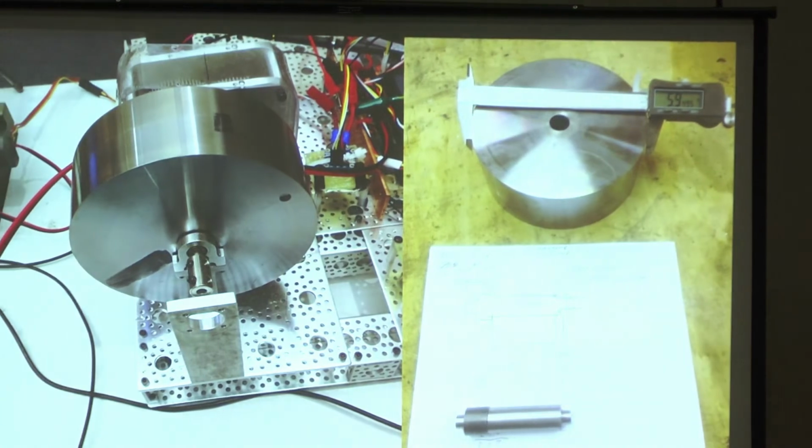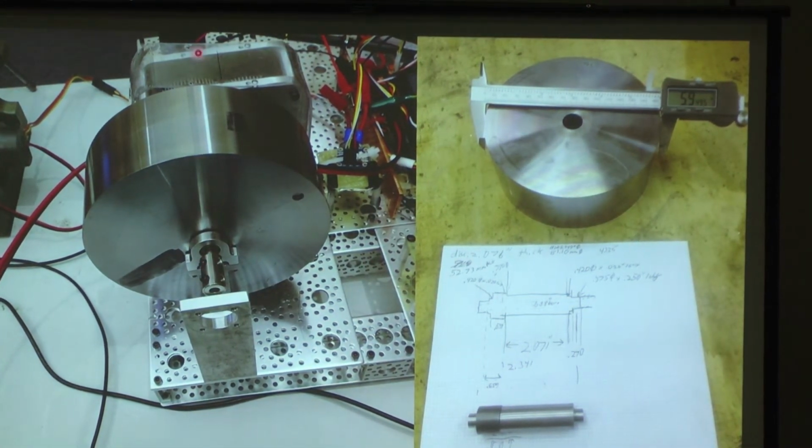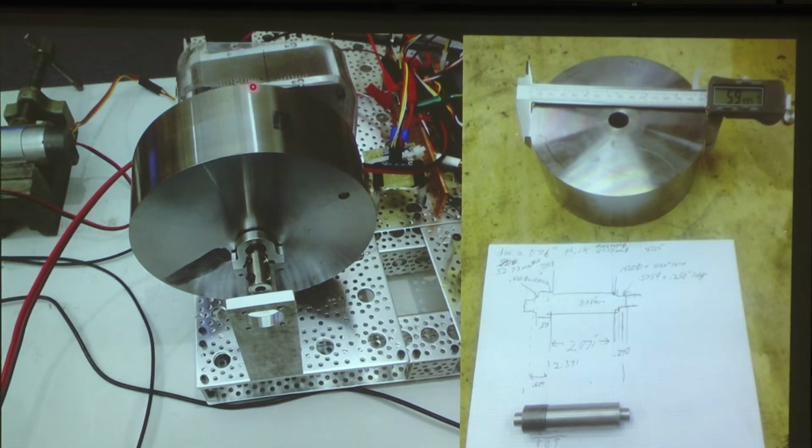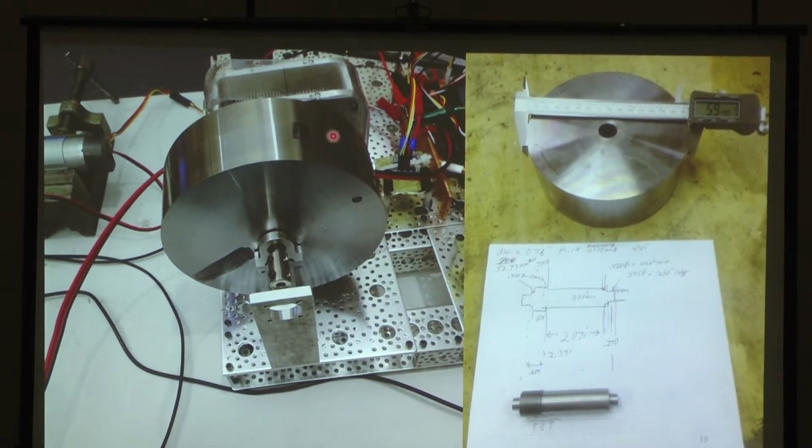So before we could collect any data, we had to manufacture many parts on our dynamometer, which we have listed here. So these are all of the parts, and I will get into that. So first we have the flywheel. The picture on the left shows the flywheel mounted on the dynamometer, and this flywheel has a bearing mount here, it has a coupler, it also has a coupler on the other side, and there's a motor mounting plate to drive it from the backside.